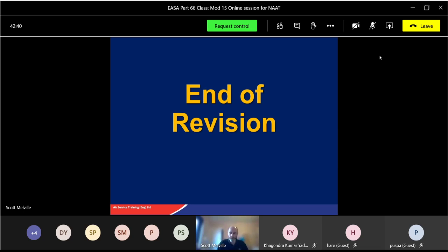How are we doing for time? Just about lunchtime. Quick one on starter systems, make sure we've got this right. A start requires what 3 things in the correct order? Rotation. Yeah. Good. It must be in that order. RFI: rotation, fuel, ignition.